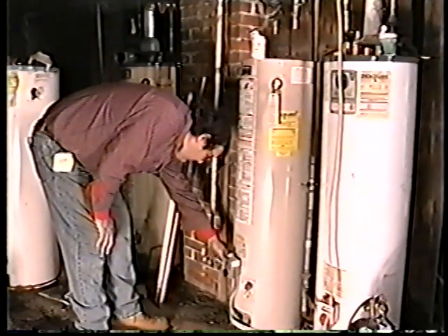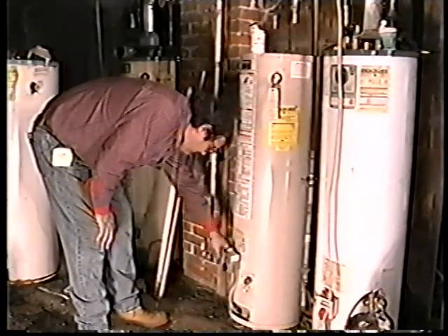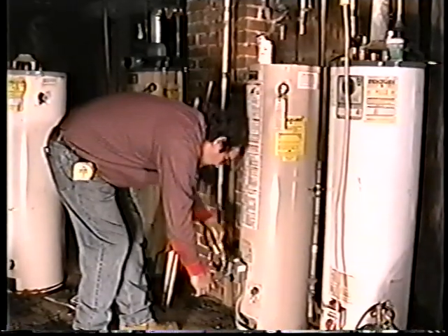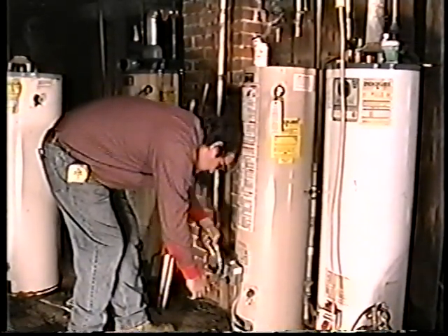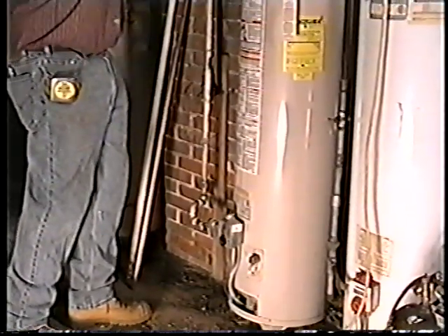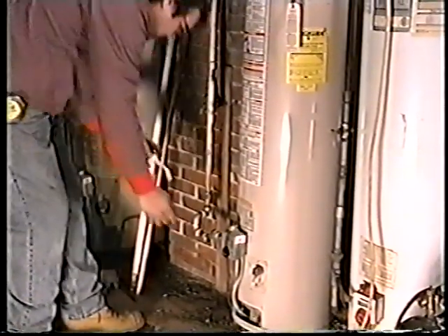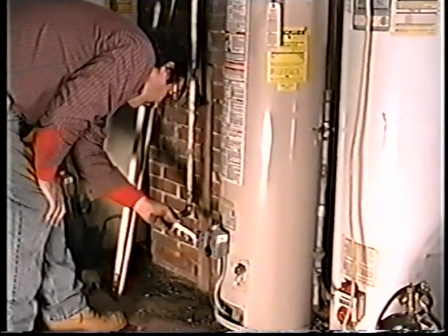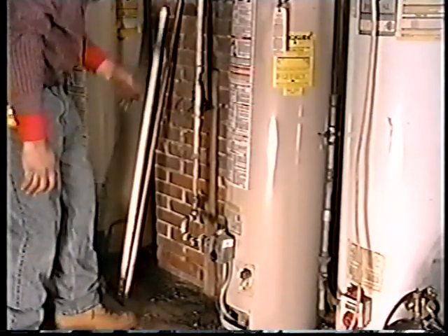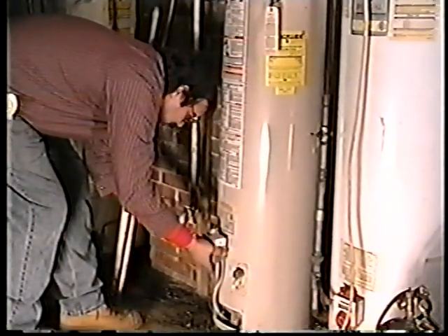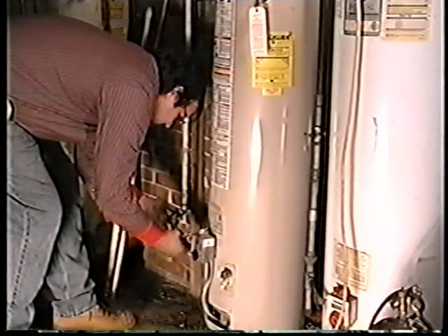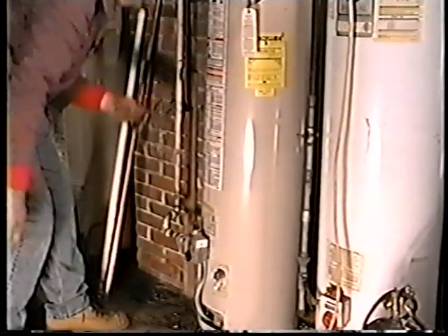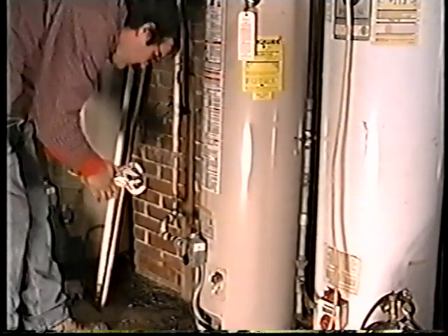Threading into the gas valve. Okay, I'm using 2 pair of pliers. Going to hold the gas valve with 1 pair so that it doesn't break or crack, and tighten in the fitting. And the last part is to connect the union together to join the 2 lines. Okay, I'm putting some pipe compound on the face of the union so that it doesn't leak when they're connected and tied together. Bring the gas pipe up and in, and connect that union together. Okay, we need 2 wrenches again to tighten the union.